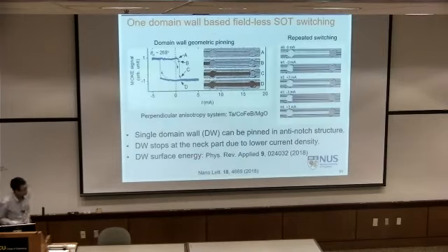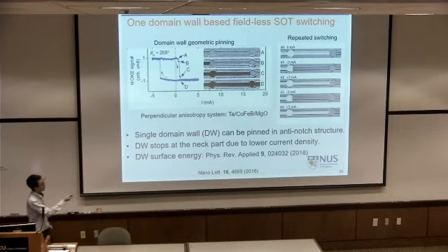All right, so once we have this domain-wall dynamics, we can also think about how to eliminate the external magnetic field necessary for SOT switching. So we can make this kind of dumbbell structure, and then we can define our domain wall at a particular position depending on the hysteresis of the magnetic field. Then once you define your domain wall, we can apply charge current into this device and move this domain wall back and forth without any magnetic field. This one again because of DMI.